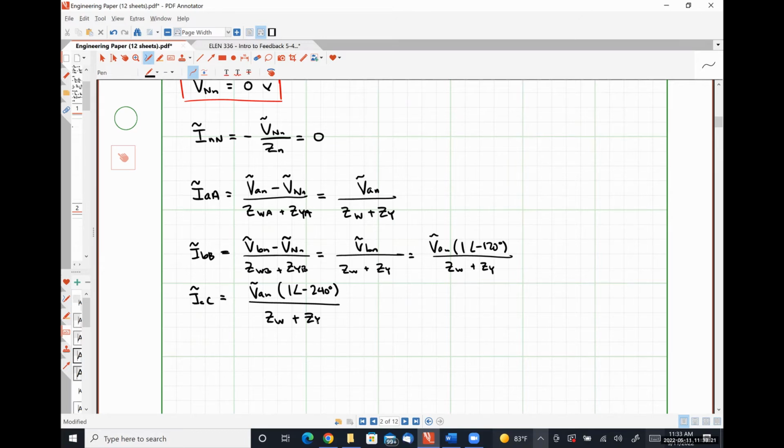And that unbalance in the system can manifest. So if it were wildly unbalanced, right? So one set of conductors is carrying much more current than the other two. If the conductor isn't rated for that, it can cause physical damage to the conductor in the form of melting, insulation degradation, and things like that. So that's why, typically speaking, we want to design things to be as balanced as possible so that we can use uniform sizing across all of the different iterations of our design, so that we don't have to say, oh, well, this part needs this. No, we just want it to be cookie cutter image of everything, and then hope that it's as balanced as we can get it.